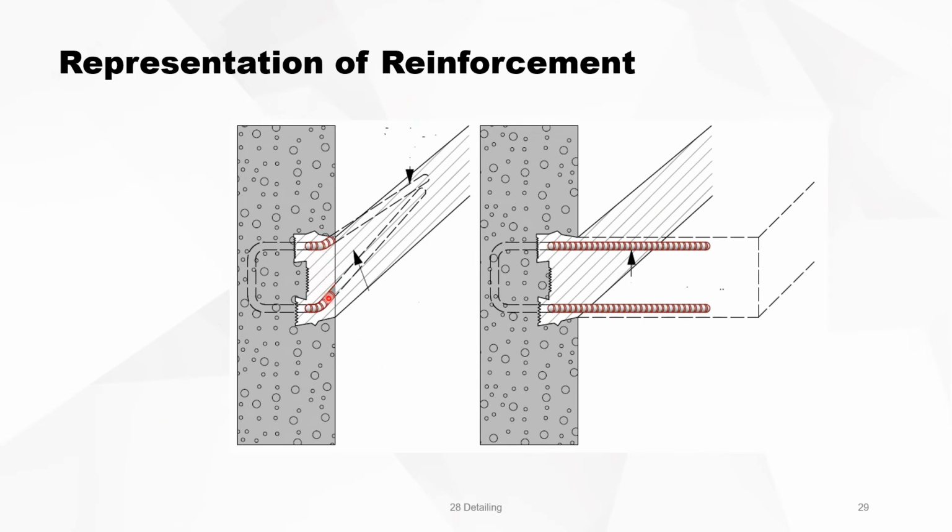This is a typical star box element. It's a box in PVC. You put it into the wall, and when the concrete is poured, you click open the box and you pull out the reinforcement to continue with the slab.